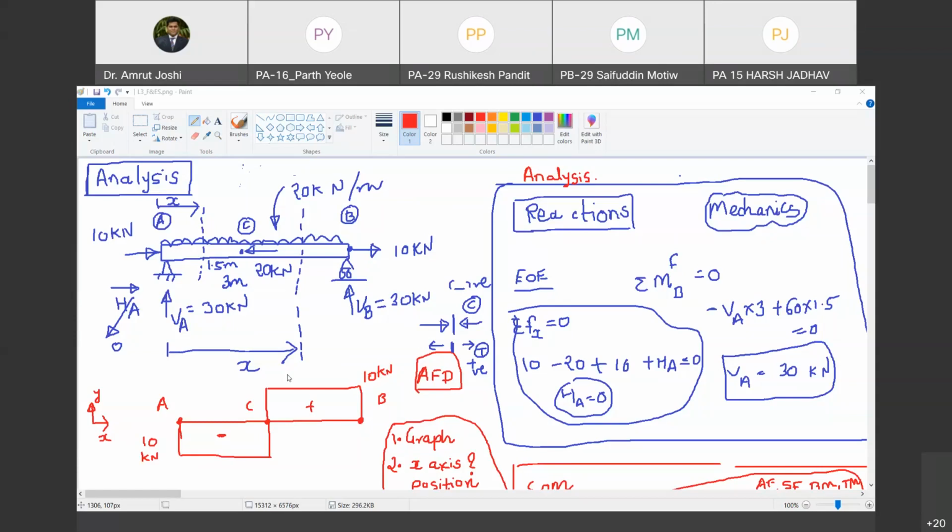Yes, sir. Absolutely. Somebody said there is a point of contraflexion. Point of contraflexion in a way says that the point about which bending moment reverses the sign, and it has to pass through zero. On either side of that point, you are going to experience contrary flexures. So if you are designing an RCC beam, if you need to provide reinforcement on top on one side, on the other side of contraflexure you will need to provide reinforcement at the bottom. Agreed? Yes, sir. Okay.